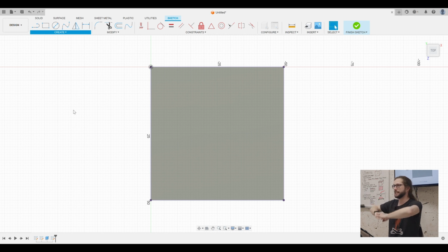We could have a plane inside the cube and use the intersection command. Okay. We could also still use the project command even if it is intersecting. It just won't do necessarily what you think, right? Because it's a shadow. Okay. So you'll get maybe some weirdness from both sides. But please keep asking questions because I don't want to lose you.